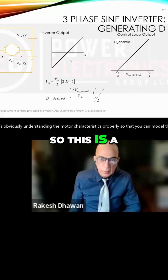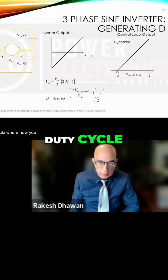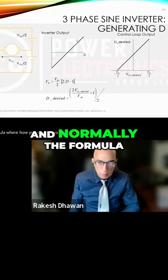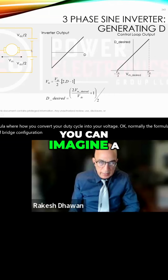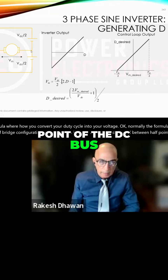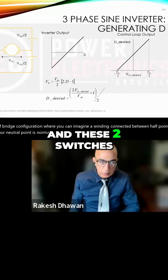So this is a very useful formula for how you convert your duty cycle into your voltage. Okay, normally the formula we use is based on the half bridge configuration, where you can imagine a winding connected between the half point of the DC bus, because that's where your neutral point is normally, right? And these two switches.